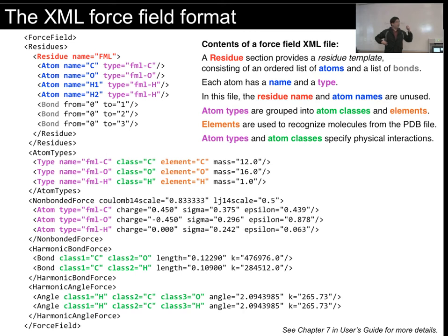But it's important to know that the parm-top and inpcrd files from Amber are not editable. They're kind of pre-digested. If you read them, they're just kind of like a sea of numbers, right? But a script to convert from the Amber force field file to this would be a way for you to become more familiar with the OpenMM format and get to use the modeling tools more and so on. Okay, any questions about this?